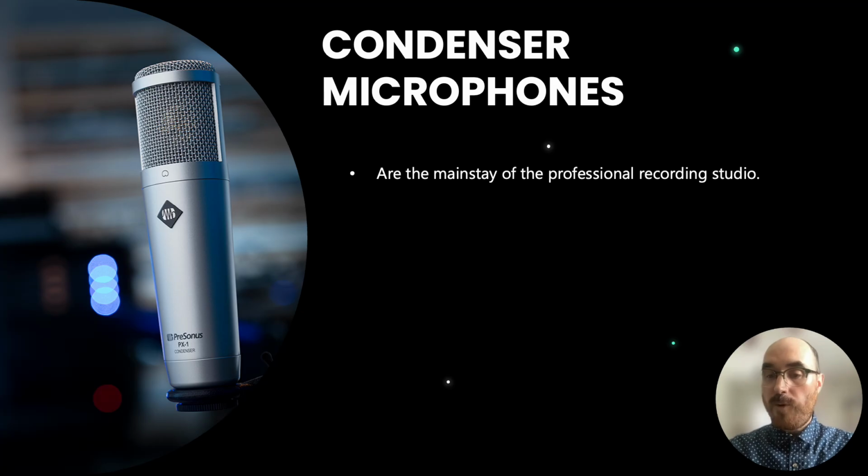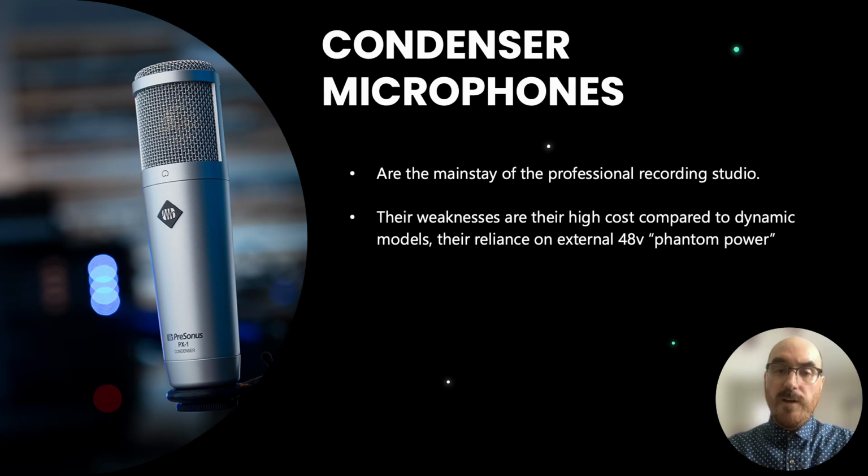If you're more of a live vocalist, you might want to have just a dynamic microphone that you really love that you can take to the venue with you. But if you're going to be doing recording, a condenser microphone is probably the way to go if you're just going to have one microphone. Their weakness lies in their high cost compared to dynamic models, and their reliance on 48-volt phantom power.